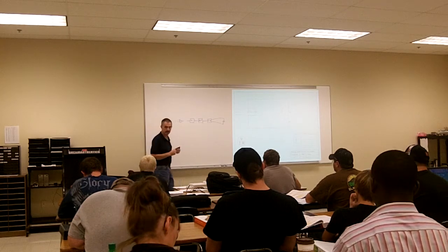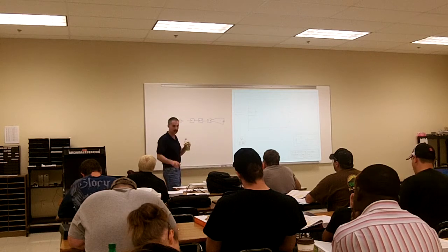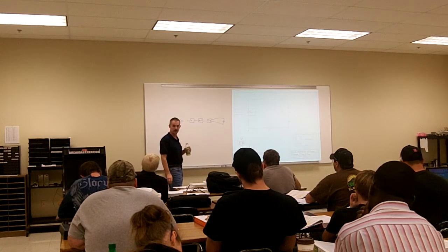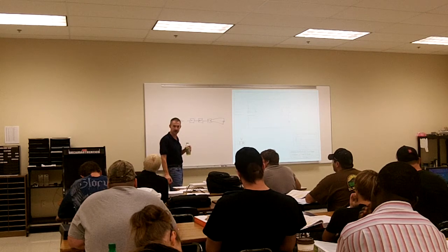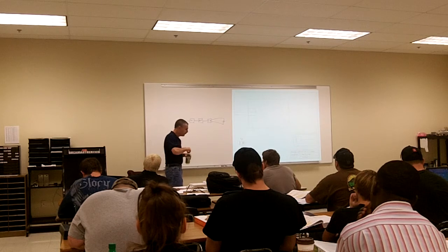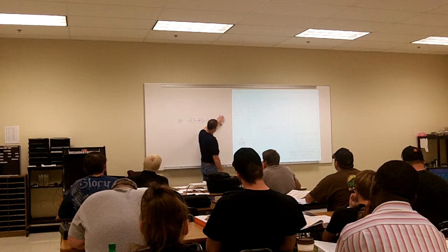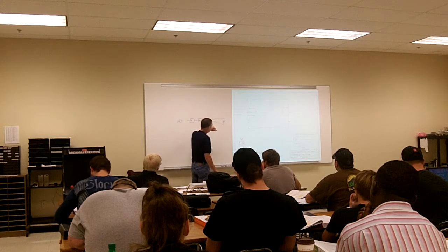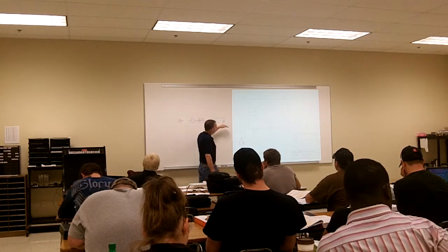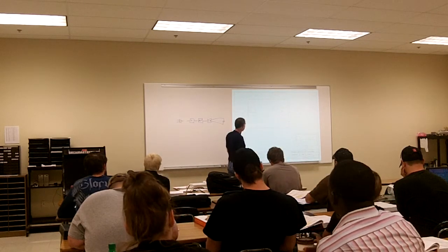Nick already measured his ohm meter, and what did you say, how many volts? 0.2 volts coming out of the ohm meter. Yeah, because the ohm meter has its own built-in power supply, so it doesn't need another power supply to do any measurements. So be careful of that. Physically remove it out of the circuit and do the measurements.